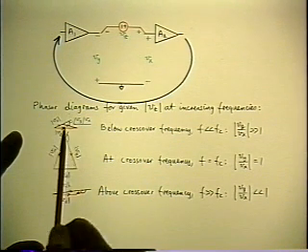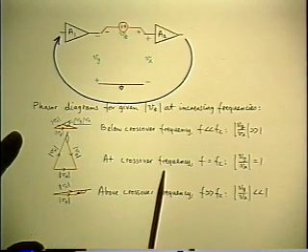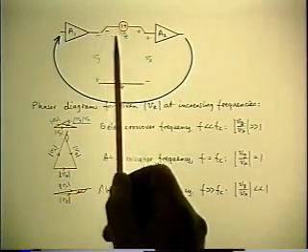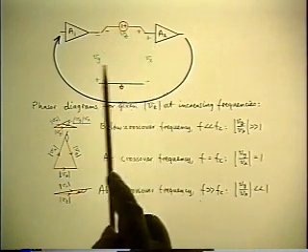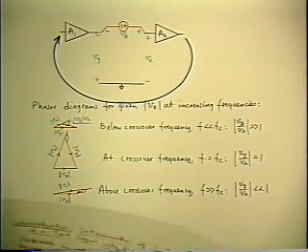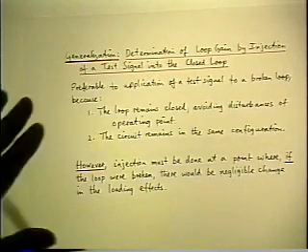So you can visualize an evolution of the triangle as you increase frequency. And you can see that followed through on the oscilloscope if you increase frequency at constant amplitude Vz and you observe Vx and Vy on a scope. You can see the magnitudes and the relative phases going through this evolution. Okay, that's a very powerful technique because of its benefits. So I've said that again right here.